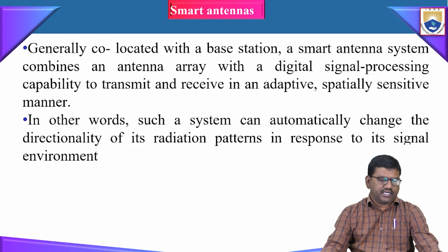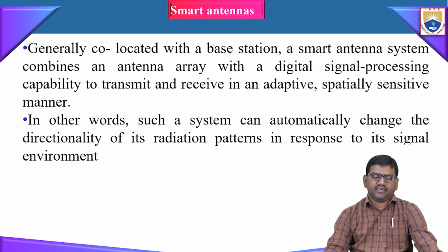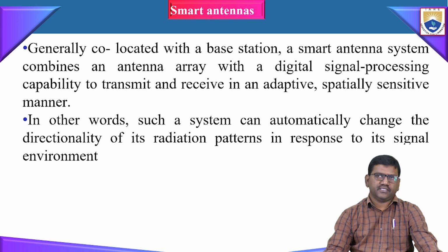The next one is the smart antennas. Generally located with a base station, a smart antenna system combines an antenna array with a digital signal processing capability to transmit and receive in an adaptive, spatially sensitive manner. In other words, such a system can automatically change the directionality of the radiation pattern in response to its signal environment. A smart antenna is nothing but an antenna where the bandwidth can be changed according to the requirement.